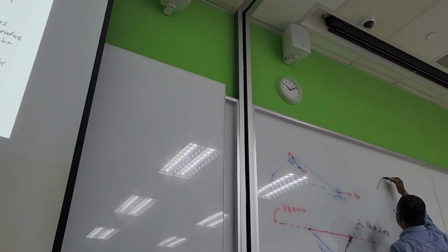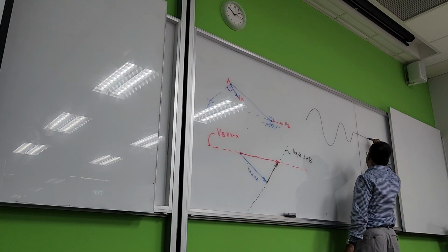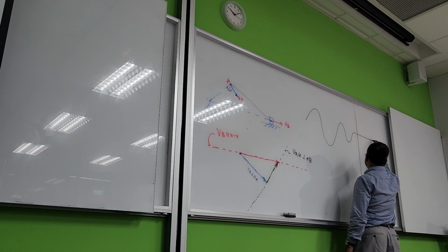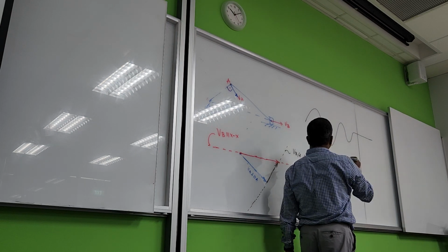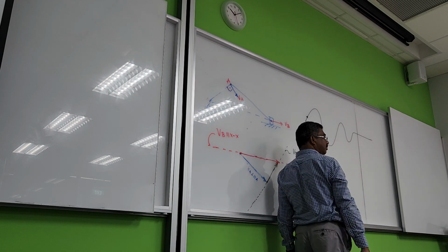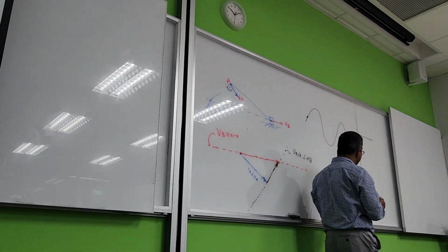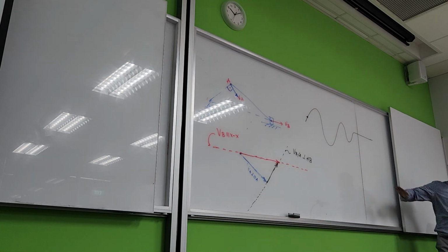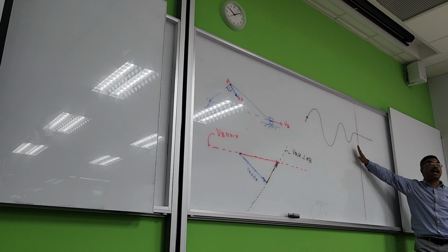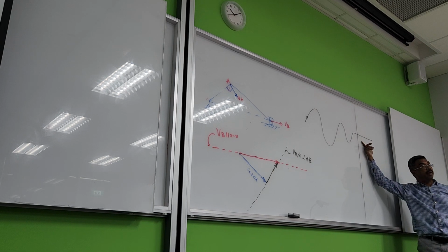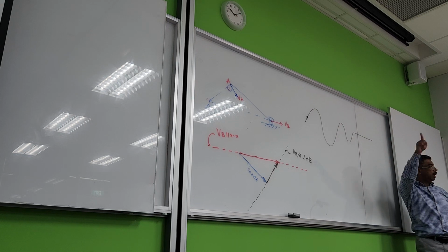Look at here. And then some section is a straight line path. So this is our car moving on this path. It is moving from left to right. That's why I showed the arrow this way. Clear to everyone? It can go in the opposite direction as well. So now have a look, young people. Our normal and tangential coordinate system can only be applied for a curved path, not for a straight line path. Clear to everyone? Only when motion is not a straight line but a rotation of a curved path.